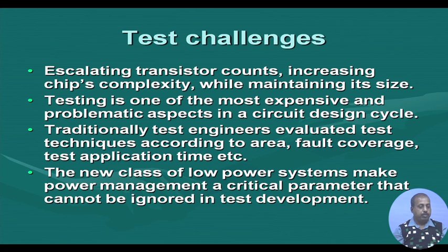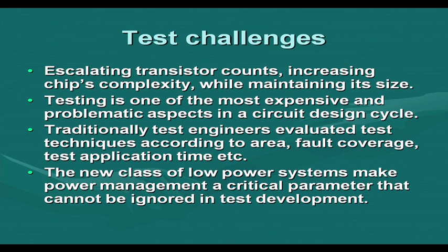Whatever techniques we have seen so far are the traditional techniques. The test methods are evaluated based on area requirement, that is, if you are proposing some DFT, what is the extra area that is required. If you are proposing some test pattern generation algorithm, then what is the fault coverage that it can produce, and what is the test application time. How much time we have to give for applying the test pattern set. These are the factors which were determining the quality of a testing scheme, including the architecture and the